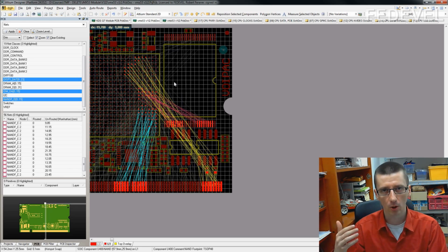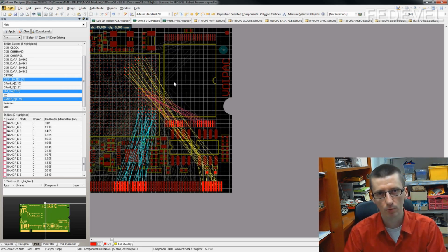We will be changing all these tracks to 50 ohm impedance, or to the required impedance. Usually it's 50 ohms. And you don't want to change the power tracks, because usually the change is to keep it 0.1 or make it even smaller. You don't want to have power tracks like 0.075 millimeter. That's not good. They should be as wide as possible. So these are two good tips which you can use during your layout.